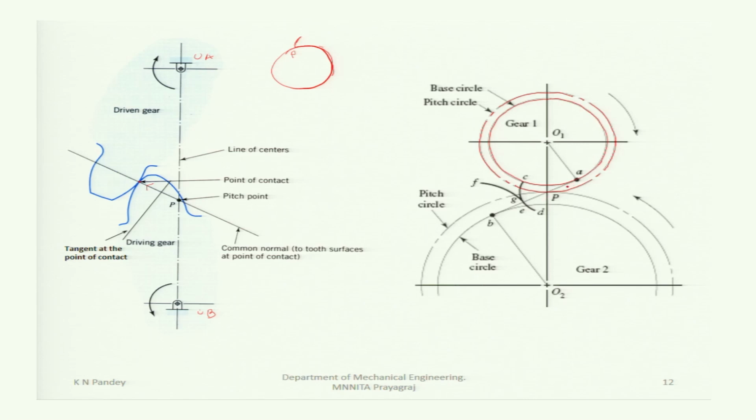And that wire, you may say, is like this, and when the wire was unwound, you have formed this profile and this profile. And you may see that the wire is wound in this way, it is passing through A, and then it is tangent to this base circle, and again it is going in this way. This is the wire.